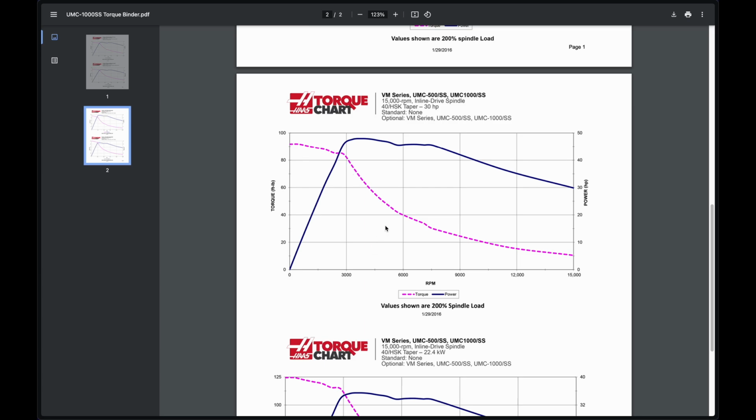So we said that this is spinning at 4,300-ish RPM, so that's somewhere over here. So we have around, let's be conservative and say 30 foot-pounds of torque and 40 horsepower. All right, so, or sorry, not 40 horsepower, 22 horsepower. Yeah, 22 seems right.